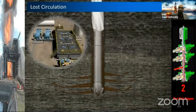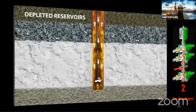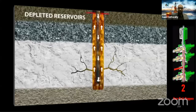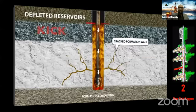But if you have loss of circulation, what will happen? You will lose your barrier, your hydrostatic barrier. For example, here we have loss of circulation through a depleted reservoir. So in this case, you will lose your hydrostatic head. The level of the mud will decrease, so you will get a kick.